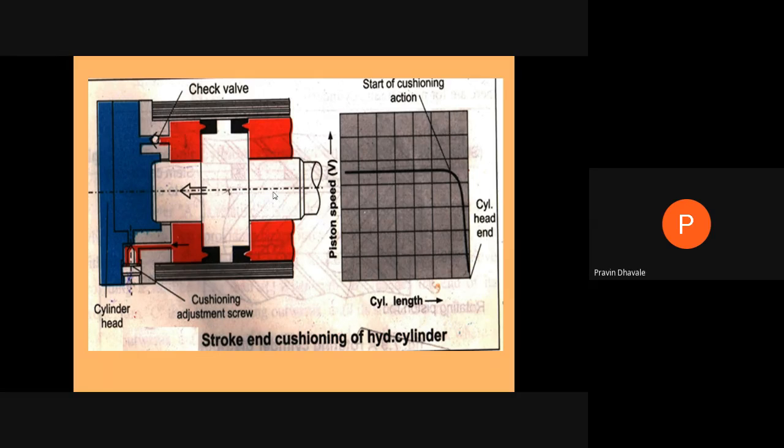So it will damage the cylinder head. In order to avoid that impact of the piston head over the cylinder head, we have provided certain arrangement so that the velocity of the piston during the reversal stroke gets reduced.